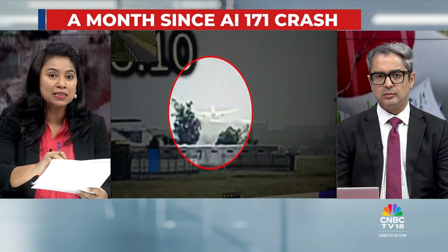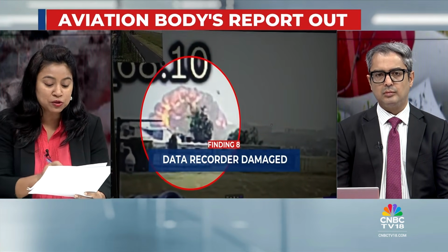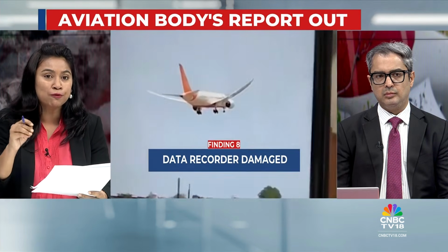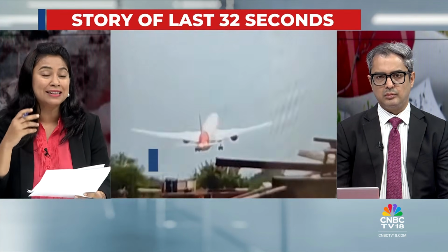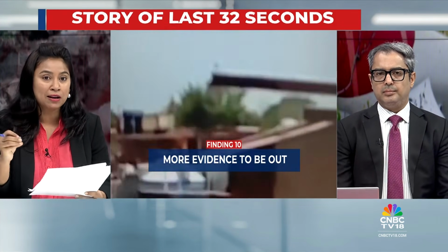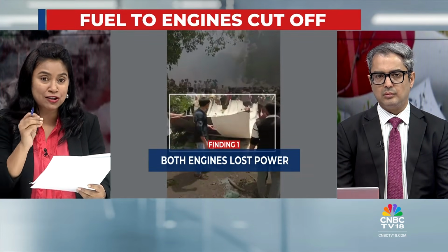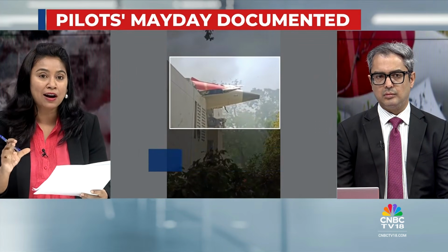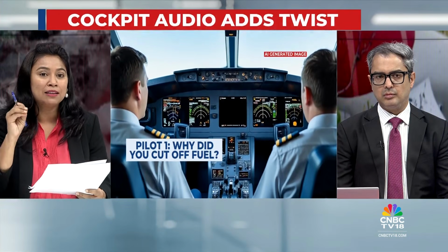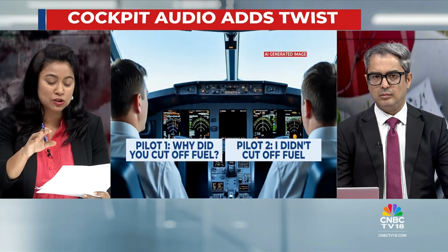It's at some point between 42 and 56 that they realize that the switch is in cutoff position and has to be taken to the run position. At 8:08:56, the second engine's fuel switch is also moved to the run position. But by then, I think the damage is already done, because relighting takes time. The engines take time after they have been cut off to once again get their power. At 8:09:05, the mayday call has been given, and at 8:09:11, the EAFR has stopped recording, which means it is at this point that the flight has crashed. So something has happened between 8:08:42 when the maximum speed was achieved, and 8:09:11.